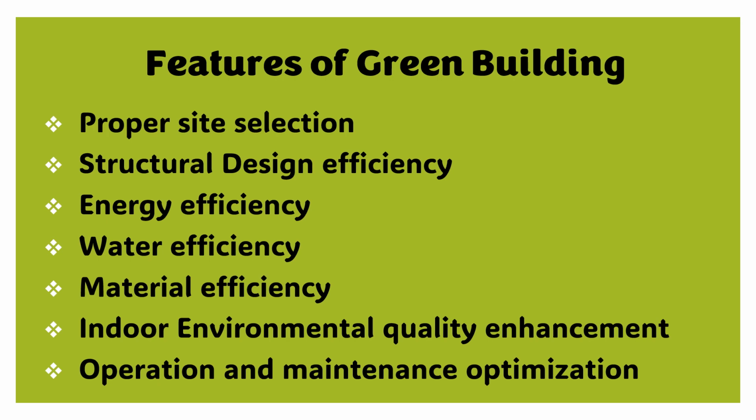Sixth point is indoor environmental quality enhancement. The three important parameters coming under this objective are indoor air quality, thermal quality, and lighting quality. In indoor air quality, the main issues include the reduction of volatile organic compounds and moisture. Volatile organic compounds will cause a bad odor and toxic emissions, whereas moisture helps the presence of bacteria and mold. The HVAC system should mainly depend on passive systems related to surfaces of the rooms and envelope of the building.